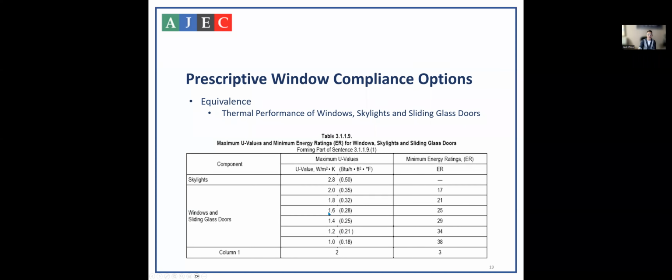Jack, I have a question for you. So the U values used in this chart here, do they include glass and frame together? Yes, it's the total. Very good question. That's a great question. Thank you for asking that. It's the overall, the whole assembly, not just a part.